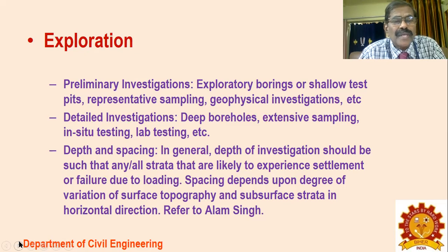So a detailed investigation can be understood only through deep boreholes, from which you can collect undisturbed samples. Other exploratory boring, like a shallow test pit or representative sampling, geophysical investigations, etc., will give only preliminary data about the soil.